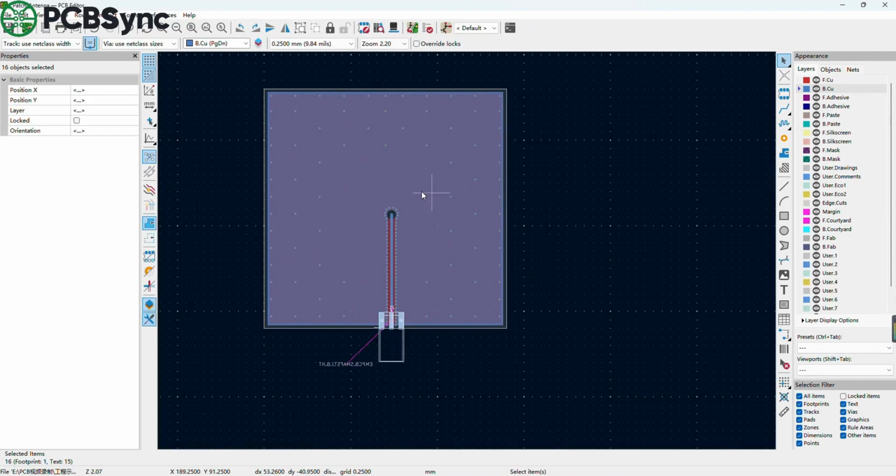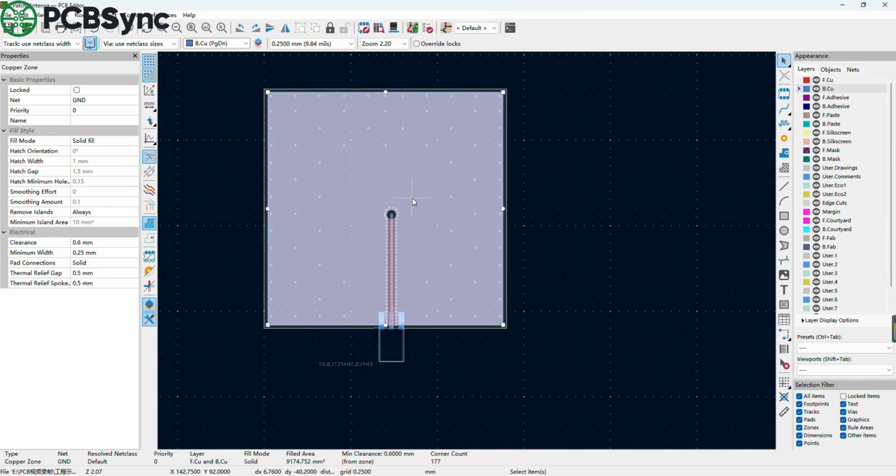Let's take a look at this patch. On the screen is a schematic diagram of an open-source patch antenna structure. The large rectangular copper area on top of the PCB is the main radiating structure, and the bottom connector is connected to the antenna through a relatively long microstrip feed line.